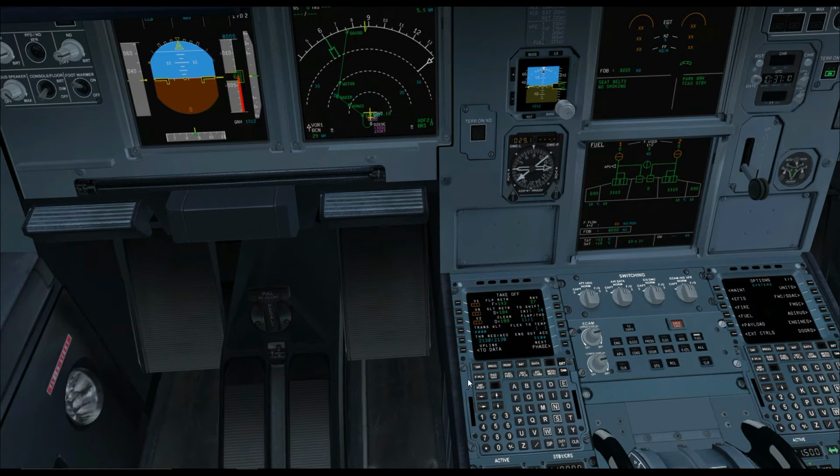For both, we don't have any specific engine out procedures, obstacle clearance procedures, or noise abatement procedures either for runway 27. So we can have a standard thrust reduction and acceleration at 1,500 feet, and the engine out acceleration can remain at 1,500 feet above aerodrome level as well.